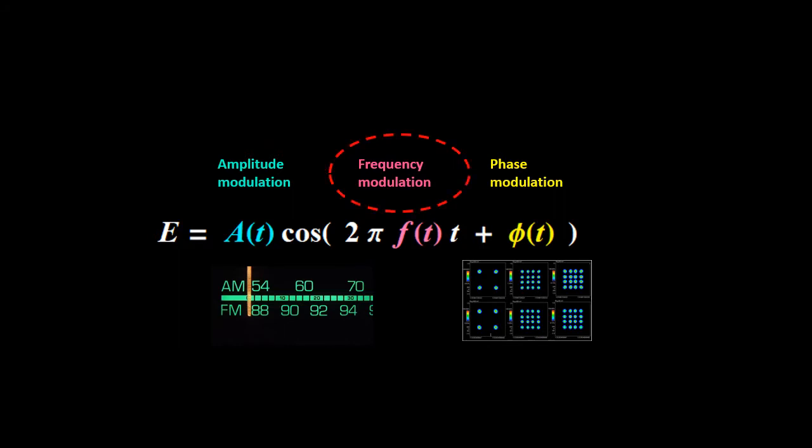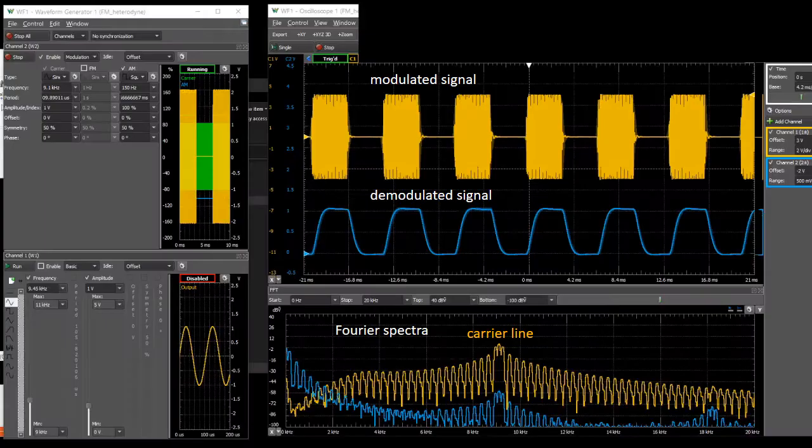In addition, Lab 6 circuits can be used to illustrate the concept of heterodyne, which can provide a foundation for one's future learning of coherent detection and high-capacity modulation techniques, such as quadratures used in phase modulation or phase shift keying. If you are familiar with amplitude modulation, you can skip this part. This review is to benefit those who have not seen the other presentations and wish a quick demonstration on the concept of carrier and signal modulation.